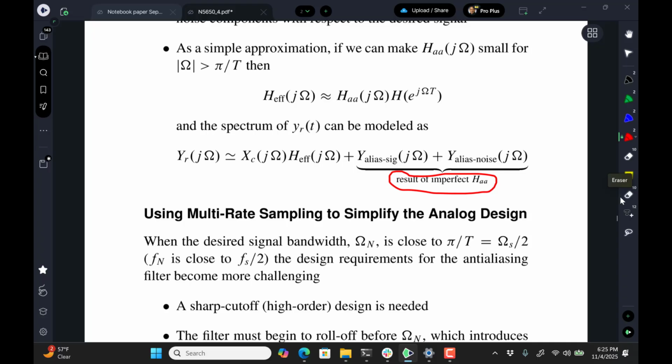They wouldn't be the correct overtone. It'd be an overtone that you don't hear because it's above your hearing, but when it folds on top, it's going to be annoying sounding. I used to have a really cool demo that I did of something like that, but I don't have the hardware to do that anymore. It was listening to a compact disc played back and then downsampling it without an anti-aliasing filter, and as you purposefully downsample it, the beautiful music of the CD sound gets all garbagey sounding when the aliasing happens. Believable? Or maybe you've heard it. There's probably a demo of that somewhere on the internet, but I used to do that in the lab.